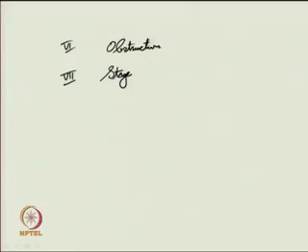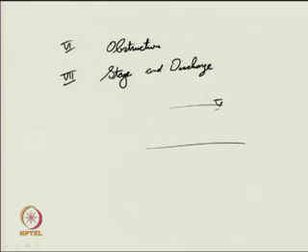Your roughness coefficient is also dependent on the stage and discharge. Normally, you may see that for a large depth of flow, whatever roughness is there in the bed may not affect much of the flow in the channel. But if the flow is shallow, whatever roughness is there in the channel bed may affect your flow considerably. So, that also needs to be taken into account while determining the roughness coefficient.